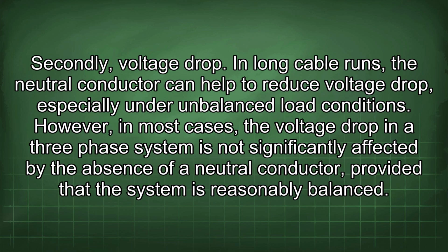Secondly, voltage drop. In long cable runs, the neutral conductor can help to reduce voltage drop, especially under unbalanced load conditions. However, in most cases, the voltage drop in a three-phase system is not significantly affected by the absence of a neutral conductor, provided that the system is reasonably balanced.